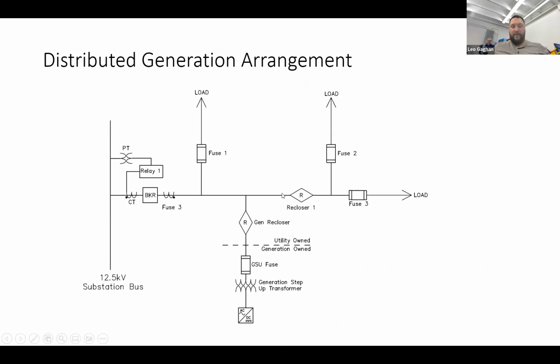So if we were to have a fault, let's say right here, the total fault current would increase because it's being sourced from the 2 different ground sources. But that actually often makes up a current divider, where a certain percentage of the ground fault current will flow through this branch of the 0 sequence network, and another percentage will flow through this branch of the 0 sequence network.